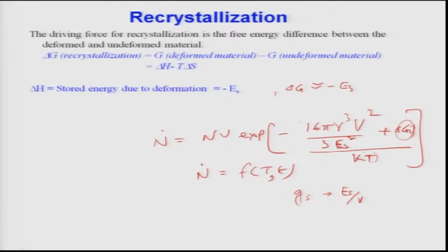It is just like nucleation rate in the case of classical solidification. If you plot nucleation rate versus undercooling, after some point it shoots up and increases rapidly, and exactly the same thing happens here, because it is an exponential of minus 1 by T terms.